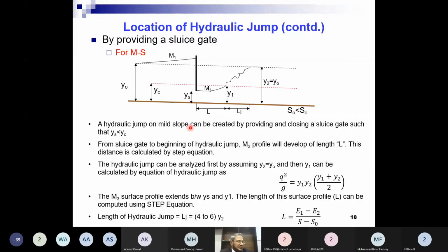How much are you getting for vs? 33.33. Yes, sir. And then compute Es, specific energy, which is ys plus vs square over 2g. How much would it be? 18.75 feet. And then next compute vm, mean velocity. Sorry, not yet, first now come to the other side. Now write y1. What is the value of y1 you got? 1.62.